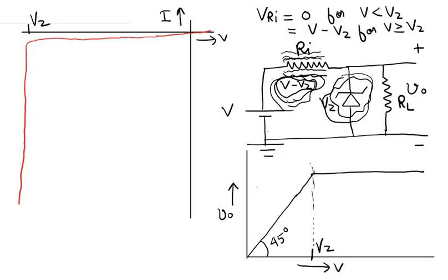This resistor Ri prevents a large excess current from flowing across the Zener diode, and prevents any voltage beyond Vz from dropping across the Zener diode. So this resistor Ri protects the Zener diode from destruction.